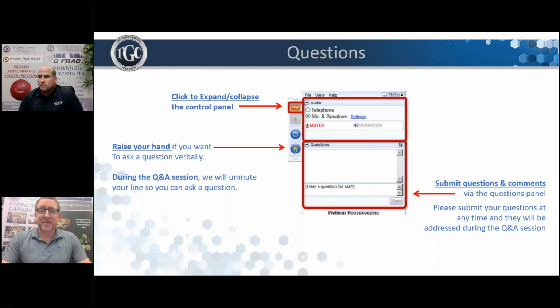Garolite G10, yeah, G10 is commonly referred to as Garolite. That's an old brand name that's been around. So can G10 composite material pass a 5,000 psi hydro test? And can G10 be threaded for assembly onto a steel or aluminum component? Kind of tackling those, it sounds like that might be a casing application, Tom, but not totally sure.